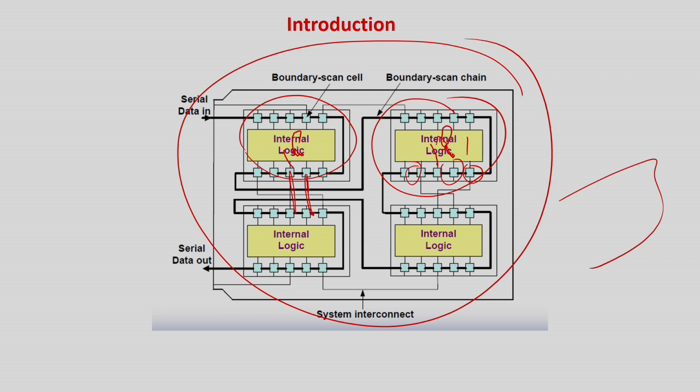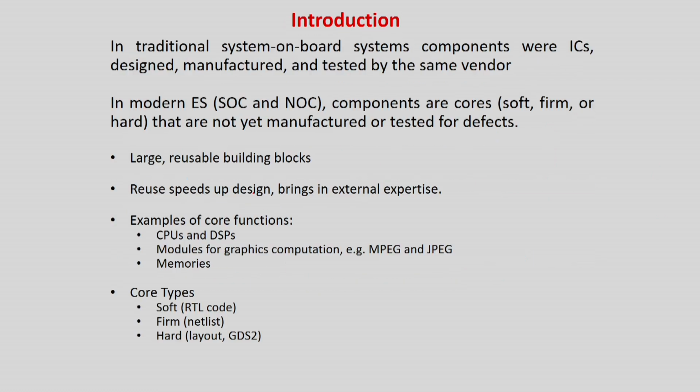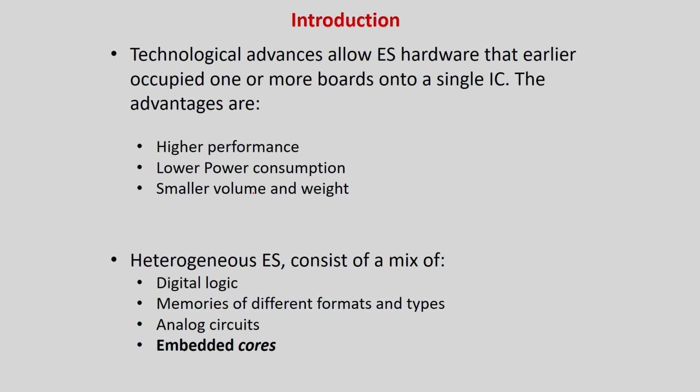But the problem is the lack of observability and controllability, because these are the pins which lack observability and controllability. How to access those pins and apply test patterns is the main challenge for embedded system core based design, which we are going to look at in this lecture. So with this picture I have given you the motivation.